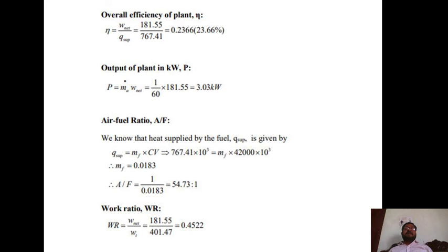That is nothing but the mass also he has given. That is 1 kg per minute he has given. But you have to supply for the kilowatt, which is nothing but kilojoules per second. But mass you are substituting in kg per minute. So if you want to get it in kilowatt, you must substitute this mass flow rate in terms of kg per second only.